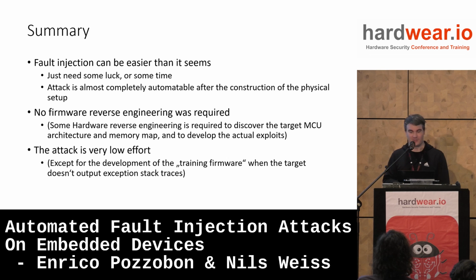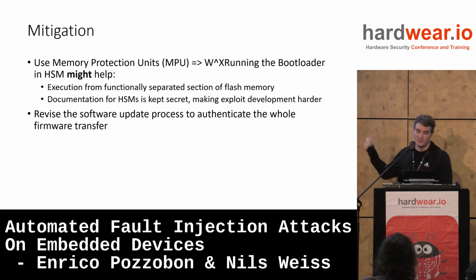The only hard part is developing your training firmware, your toy example firmware, if your target doesn't already emit stack traces. And for mitigation, you can try to use the memory protection unit, enabling something like write or execute, and running the bootloader in the HSM might help. We don't have publishable results about that yet. We saw some manufacturers running their entire bootloader in the HSM, which has worked to stop us for now.